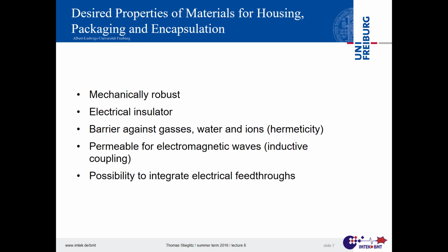And how can you do that? I mean, either you make a barrier, then water cannot penetrate, or you put something on your electronic circuit that sticks there so tight that the water cannot condensate. The effect is the same, your device survives, but the mechanisms are different. And that's one of the important take-home messages. There are materials that are not hermetic, but if they stick well, I can prevent water from condensation, and then no corrosion occurs.